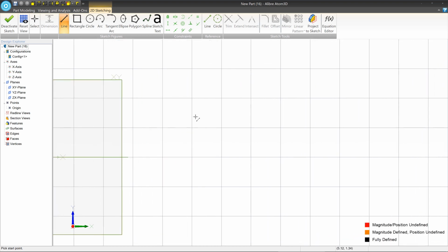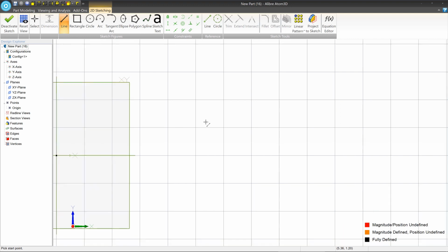Constraints, before we get into the sketch, are basically real-world limitations on what the geometry can do. The sketch constraints all live up here. There's the lock or the fixed constraint, symmetric, co-radial, collinear, equal, vertical, coincident, concentric, perpendicular. There's a whole bunch of them. And basically what they do is they apply some limitations to what your sketches can do. So I'll show you with an example.